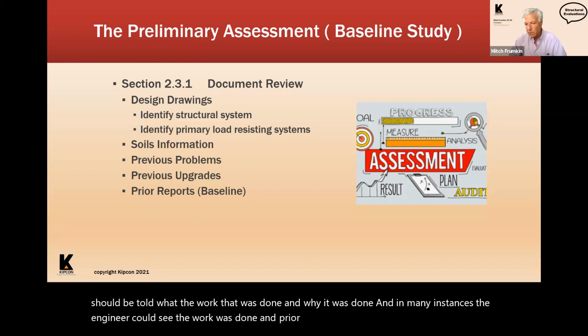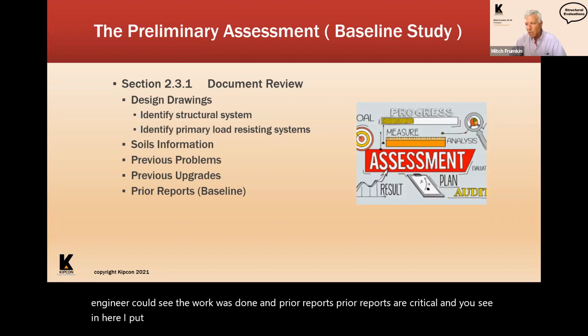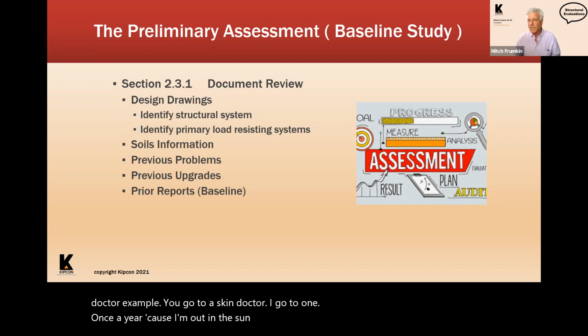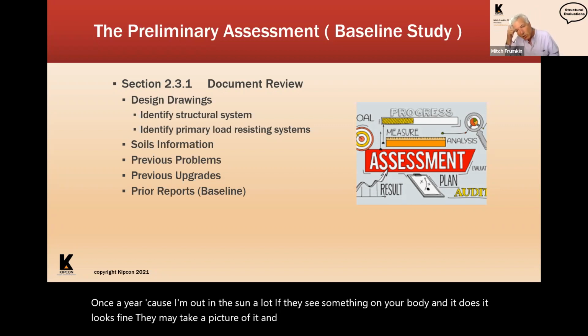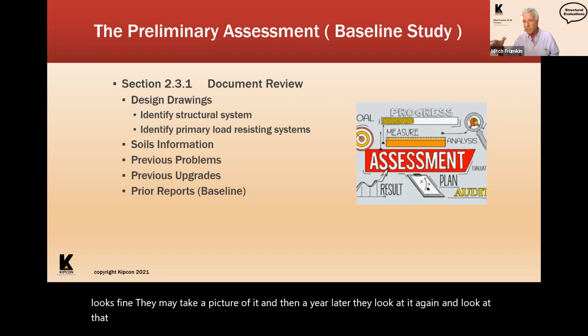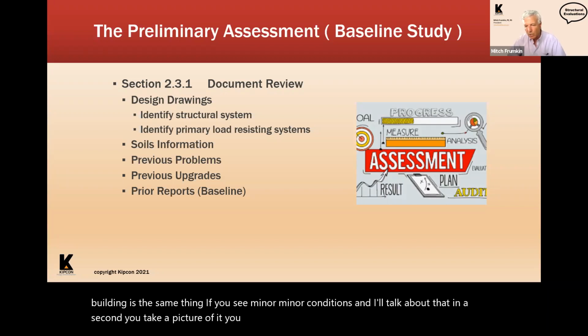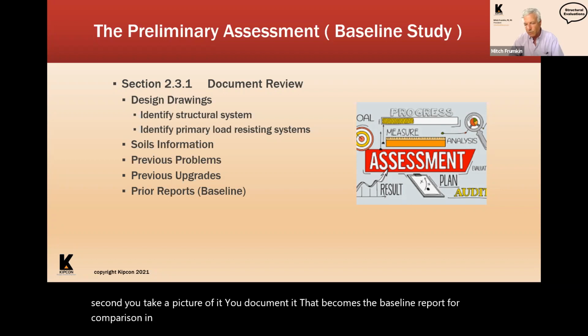And in many instances, the engineer could see the work was done, and prior reports. Prior reports are critical. And you see here, I put the term baseline. What I mean by baseline is, and I'm now using the skin doctor example. You go to a skin doctor, I go to one once a year because I'm out in the sun a lot. If they see something on your body and it looks fine, they may take a picture of it. And then a year later, they look at that picture again to see if it's gotten worse or something's happened. The baseline report for a building is the same thing. If you see minor conditions, I'll talk about that in a second, you take a picture of it, you document it, that becomes the baseline report for comparison in the future when the next report is done.